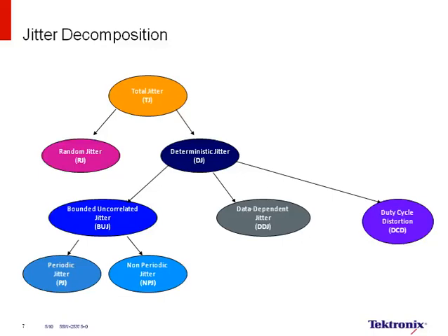Total jitter is an example of an estimation technique. You may have heard of the term Dirac and an equation where TJ is approximated by 14 times RJ plus DJ. That 14 that you see that's multiplied by the standard deviation is an attempt to predict what the peak-to-peak jitter is by multiplying 14 by the standard deviation and adding the periodic jitter component to it.